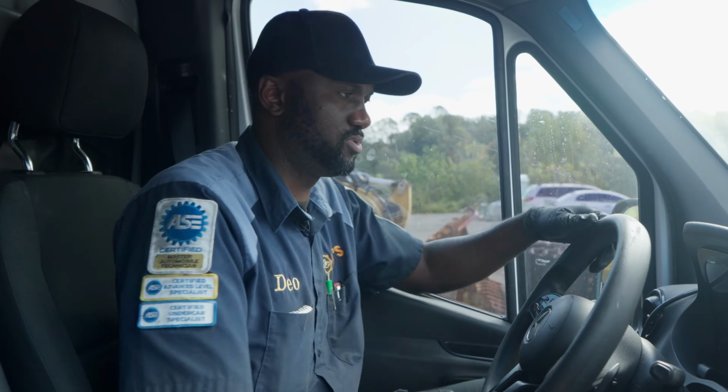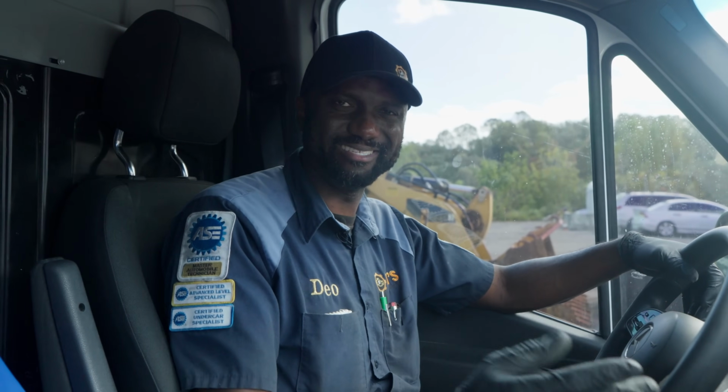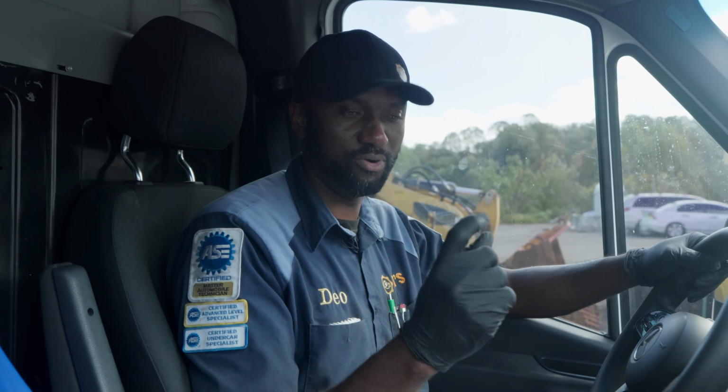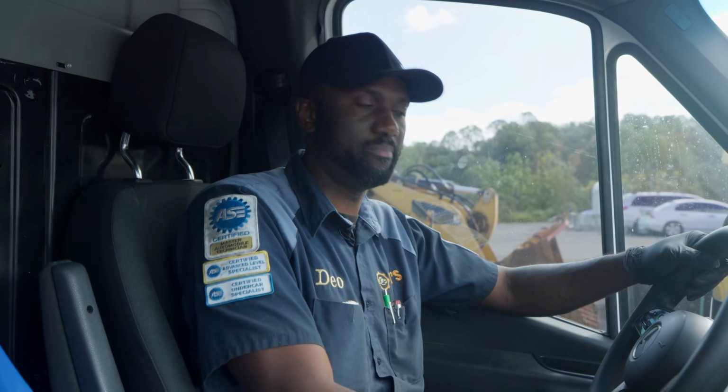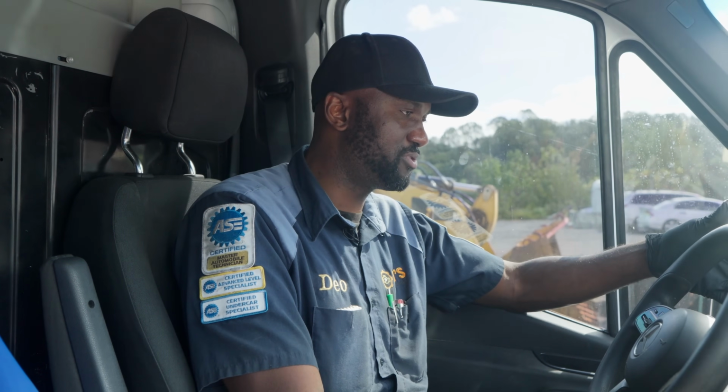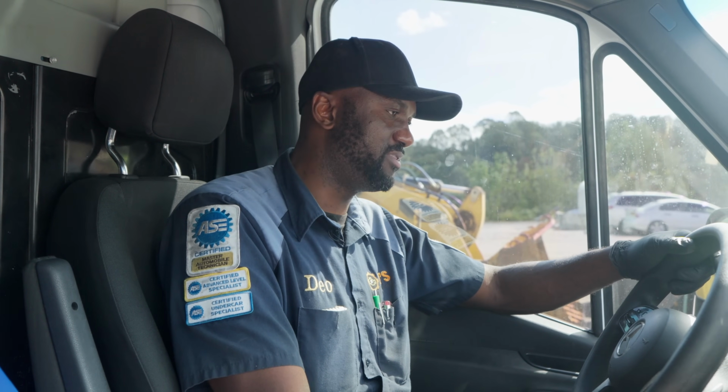All right, guys, so I'm gonna leave this right over here. This is fixed. We're gonna have another happy customer. We didn't have to remove the engine to fix this. The issue on this one was the solenoid on the oil pump. That solenoid had too much resistance. And this vehicle has 146,703 miles.